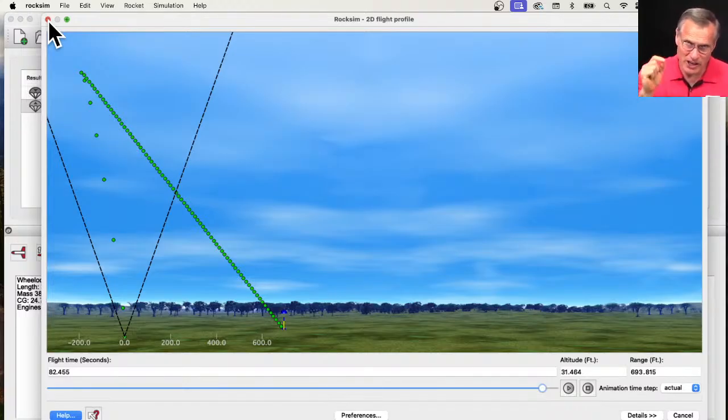If it's going to be greater than 8 miles an hour, choose the short delay because the rocket's going to weathercock more. And if it's a calmer day, the winds are less than 8 miles an hour, then use the longer delay. You still want to watch that it doesn't weathercock. That's the only thing that I'd be concerned about.